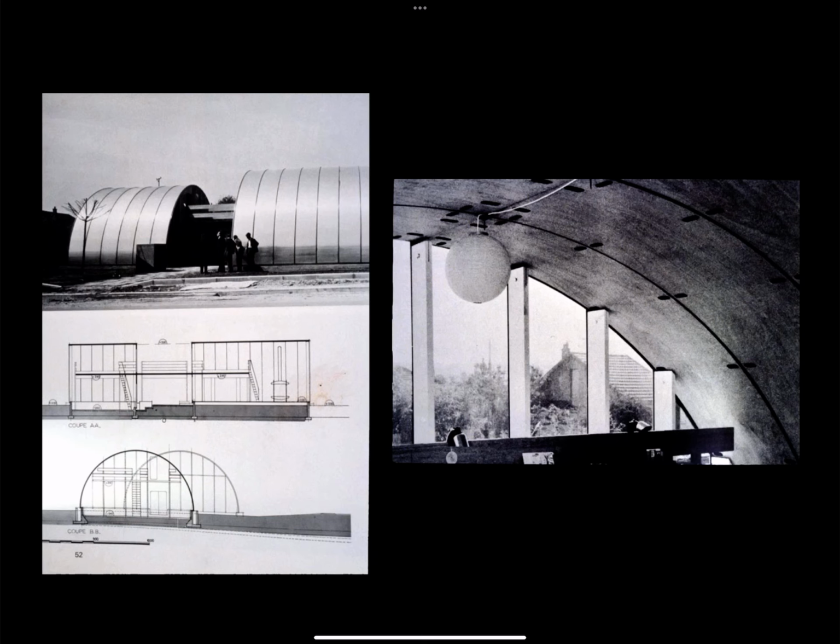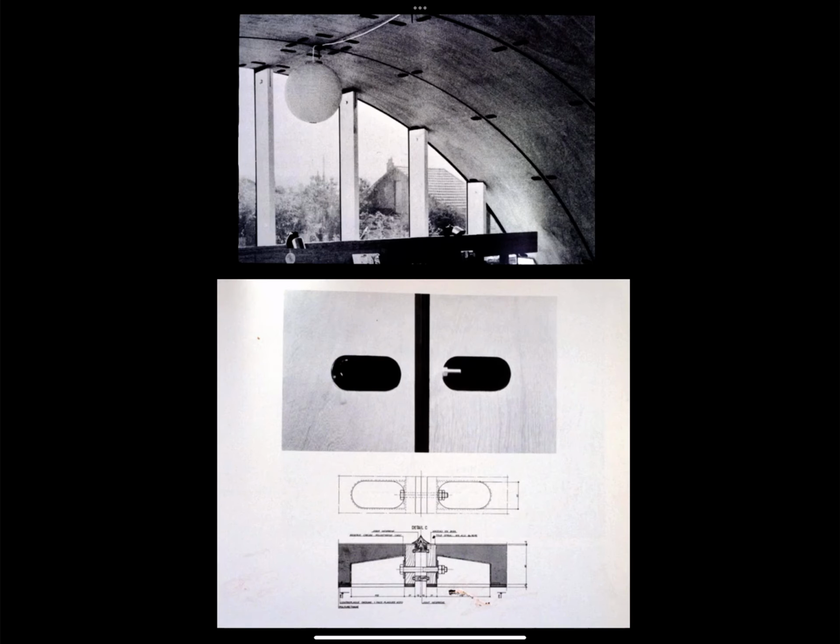The innermost layer is plywood, a thin layer of plywood, and then there's a thick layer of rigid insulation, and on the outside then a very thin layer of aluminum. And the jointing system is, so here you see the section of the panel at the bottom with the wood on the inside, the thick layer of rigid insulation, and a very thin layer of wood on the outside.